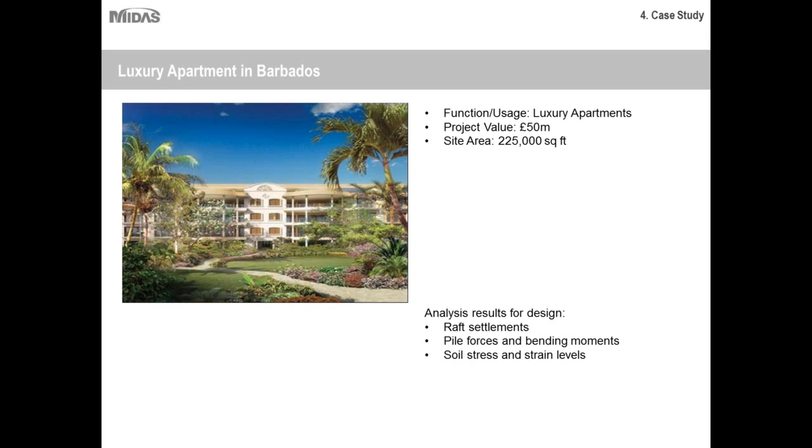And although the load from the superstructure was not that significant, and it could have been dealt with a different set of group pile arrangement, since the soil strata was not stable enough and it was a very flat structure, they decided to go for pile raft foundations, and they were interested in raft settlements, pile forces